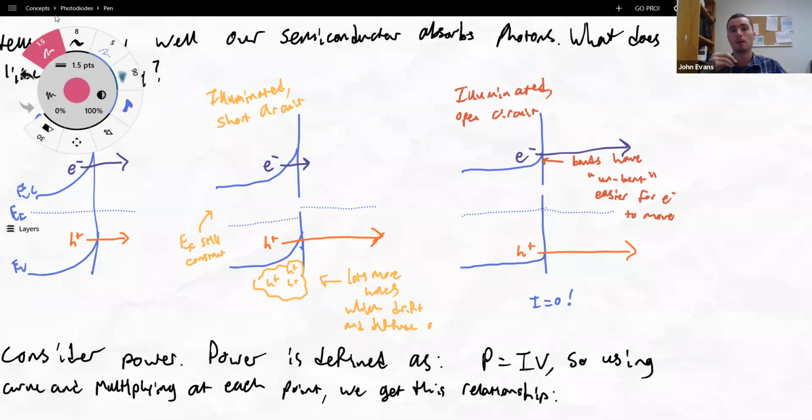Remember before, what we were doing is we were changing the concentration of electrons and holes in the conduction or valence band based on the number of dopants, right? And doing that modulates where the Fermi level is. So I was wrong before to say that the Fermi level is equilibrated. This is incorrect. In fact, what happens is your Fermi level is going to go down a smidge because you have increased the concentration of holes down here.